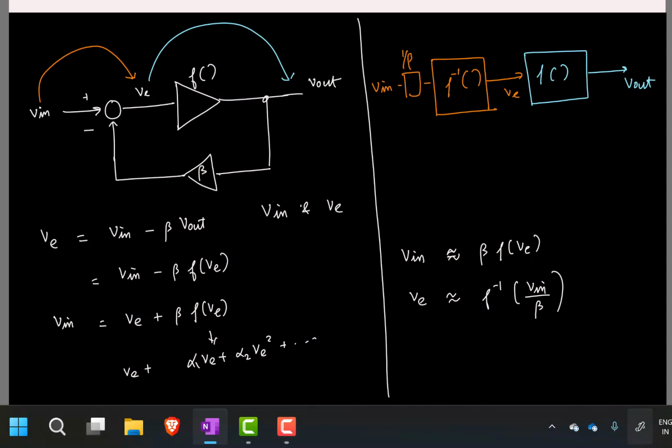So technically, this is called pre-distortion. That is, we have some nonlinear function that is distorting it. You have an inverse function of it and pre-distort the signal so that when that is going to the actual nonlinearity, those two get cancelled and you get a purely linear operation.